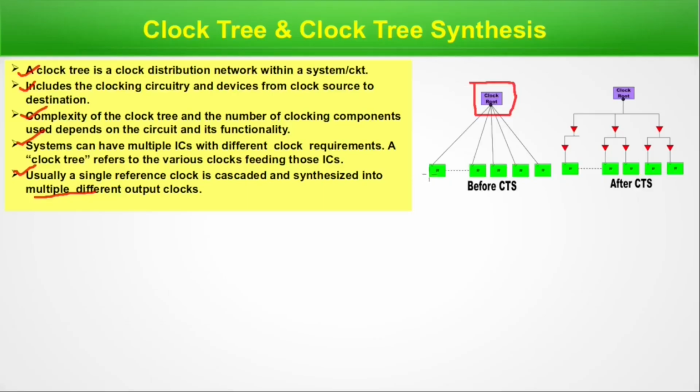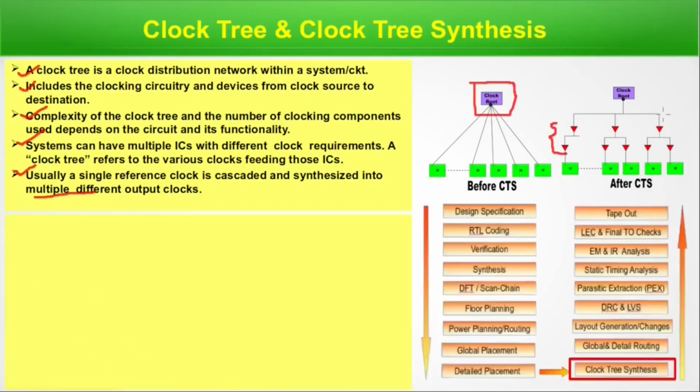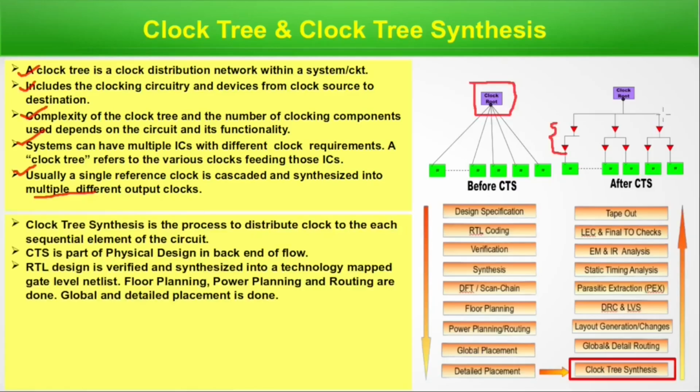Clock root is the source and the destination is a leaf level flip-flop. Before synthesis, it's directly connected. After synthesis, that connection has been cascaded through some buffers. This level of buffers gets included in CTS. This is the contribution of CTS.